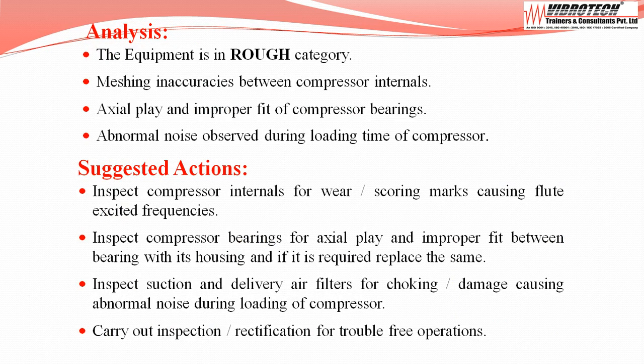Based on the analysis, the following actions are suggested. Inspect compressor internals for wear and scoring marks causing the excited frequencies. Inspect compressor bearings for axial play and improper fit between bearing and its housing, and if required, replace the same. Inspect suction and delivery air filters for choking damage causing abnormal noise during loading of the compressor. Carry out inspection and rectification for trouble-free operations.